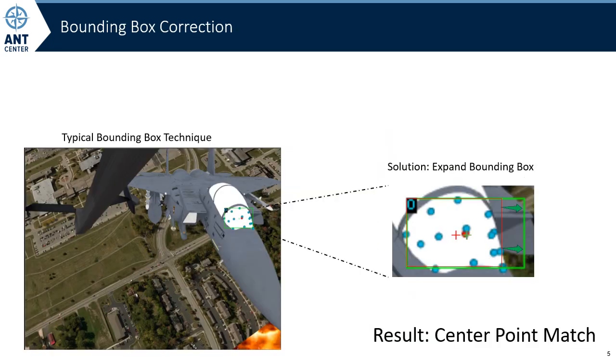However, if we train our neural network on components of an aircraft that are defined in the typical way object detectors are trained, then issues arise. The typical way is to define a component, seen in this image as a point cloud, project those points to the screen, omit points that are occluded, then draw a box around those points. The issue from this is that the 3D geometric center will not match the center of that bounding box, which means the perspective endpoint calculation could be incorrect. This is for two reasons.